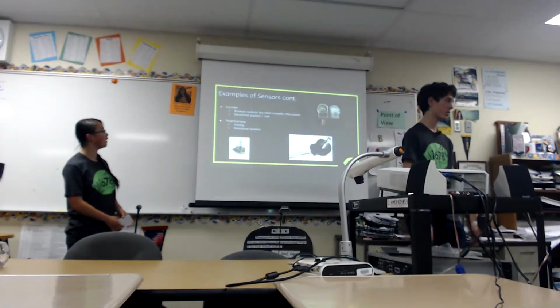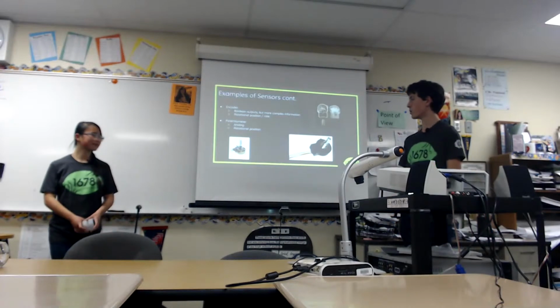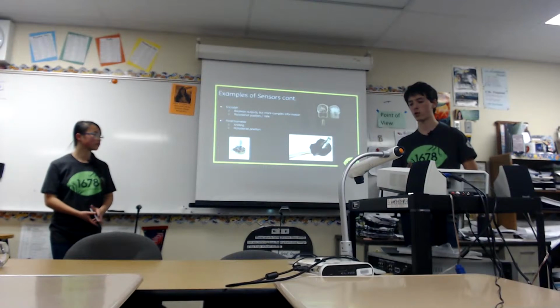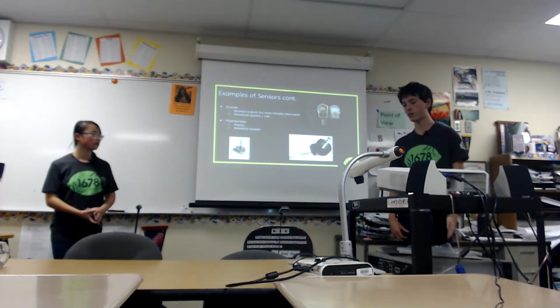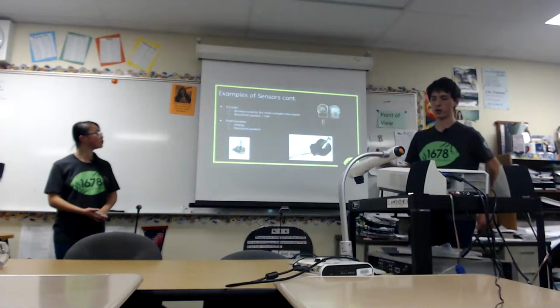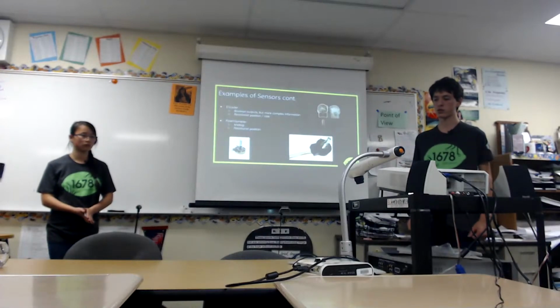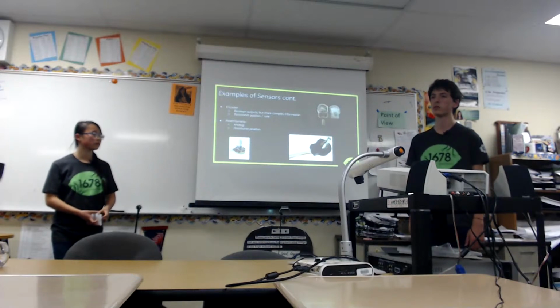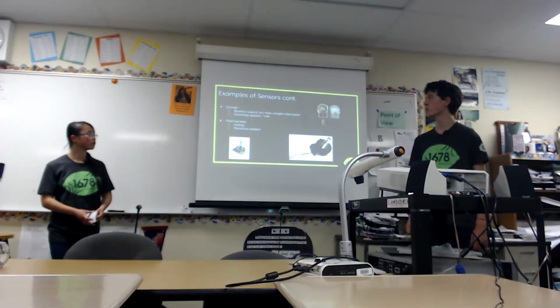All right, next slide. Okay, so with encoders, you don't necessarily have to use them for a drivetrain. You can use them for an elevator, and measuring how fast your elevator rises can be useful in certain situations. There are also not just magnetic encoders. There are physical encoders, which usually have a 5-pin output, but you don't need all 5, you just need 4. One of them is an extra signal pin.